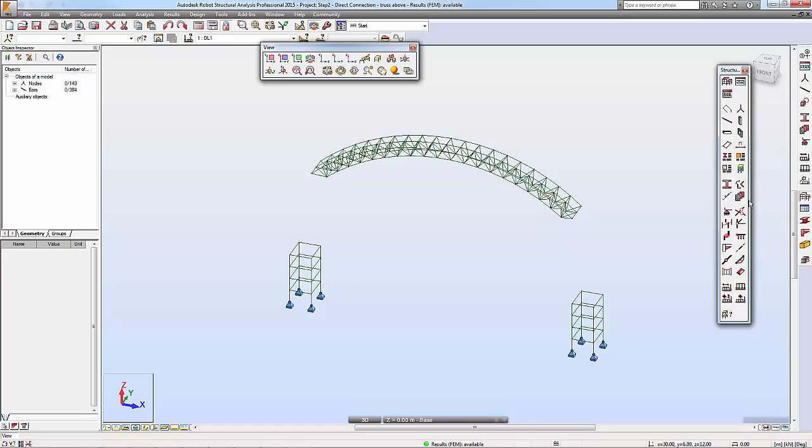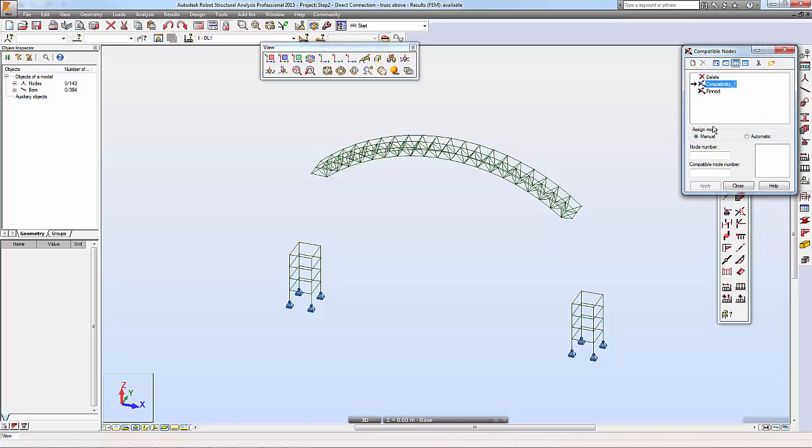If we use the compatibility, one problem we have is that we already set up this compatibility problem for this one. As we said before, we want to put rollers on this one, which allow it to roll along this direction, and then only y supported, z supported, but no x. So the first thing we need to do is delete the compatibility. We don't need to do anything to this side, assume they're linked, but lower on the other side.